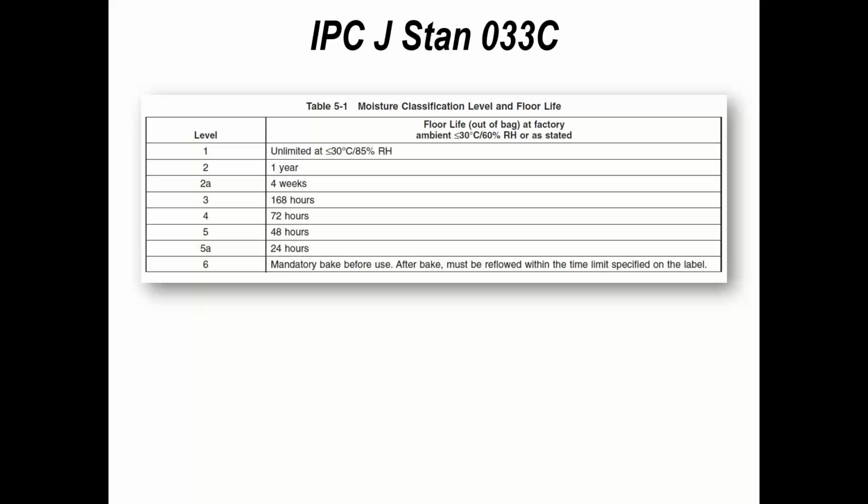But the important thing is, what does the component manufacturer say, or what does your customer say when we're talking about moisture sensitivity levels on particular components? So you have a guideline in terms of the time the components can be on the shop floor in an open environment, i.e. that is out of the protective packaging. You, of course, have got the ability to repackage packages. You've got the ability to bake packages after they've gone outside of their limit, their time limit, if you like. You also have the ability to restore them in dry boxes or dry cabinets, etc. You need to manage the situation. That's what it's all about.